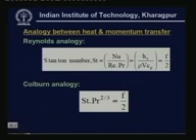So what is the use of this Reynolds analogy? You can see that Reynolds analogy connects heat transfer coefficient Hc with friction factor f. That means if we know the friction factor, you can find out the heat transfer coefficient by applying this analogy. You do not have to carry out any heat transfer experiments. So this is very useful. This Reynolds analogy is strictly applicable for Prandtl number 1.